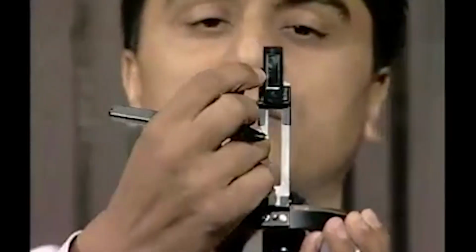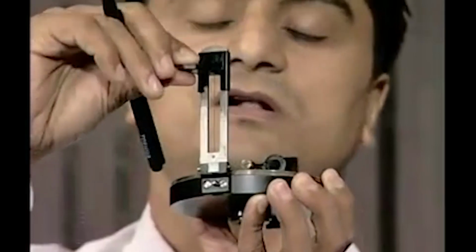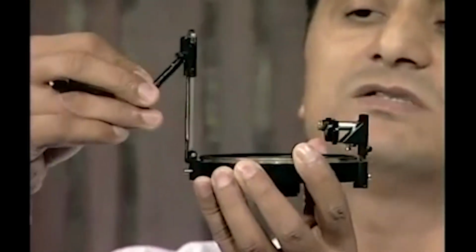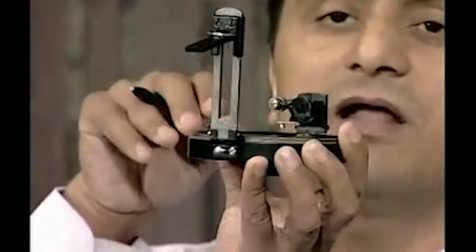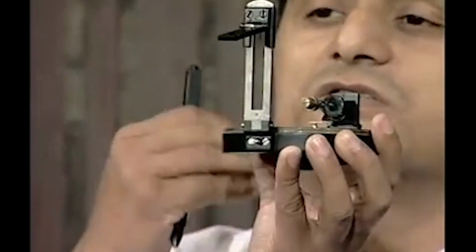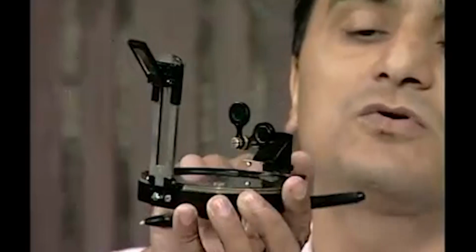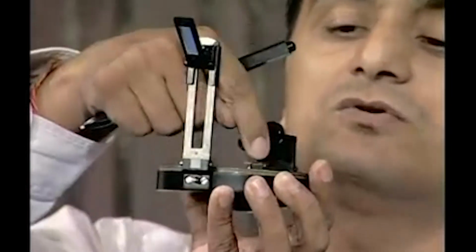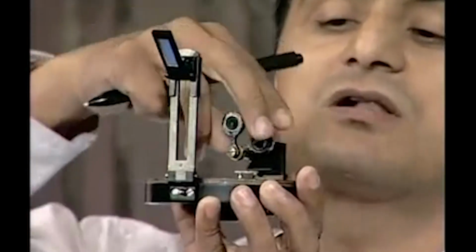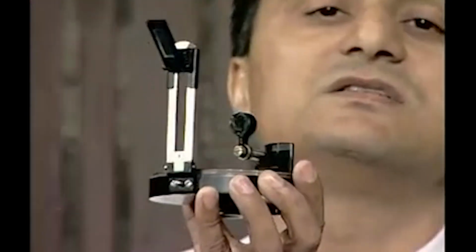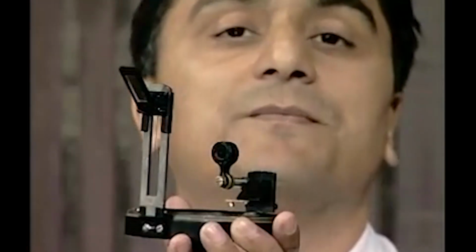Over here you will see there is a mirror also, fitted here. We can tilt this mirror, and the use of the mirror is when the lines of sight are inclined. For example, the ranging rod is not horizontally in front of me, rather down there, so I can see the ranging rod in the reflection through the mirror. Also we have some color glasses here. Because we are looking through the slit, we need to see the readings here, so color glasses help us reduce the intensity of light when required.